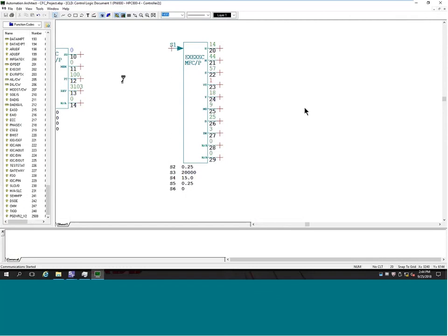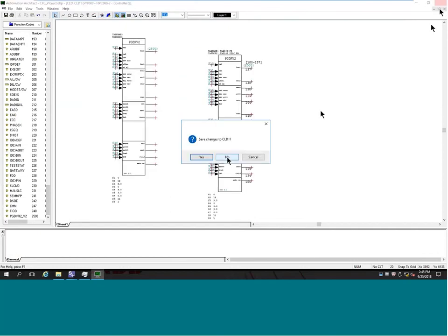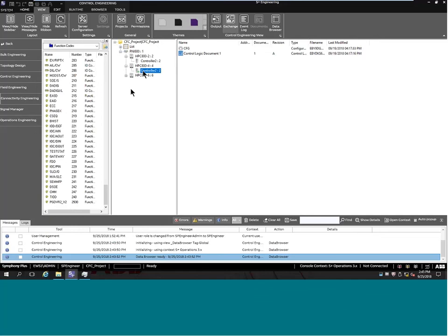And if you had multiple logics in here, you could have some on-off blocks to force some values through, and you can actually see how your logics will react live, which is a really nice feature. We use this a lot now. And if you wanted to remove it, you just come here and say disable soft controller, and then now it's off.